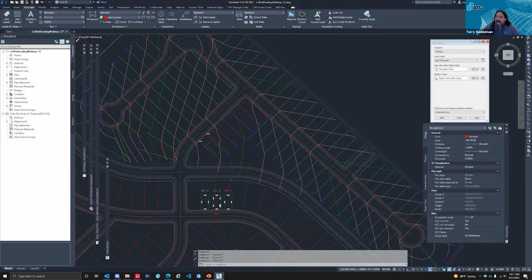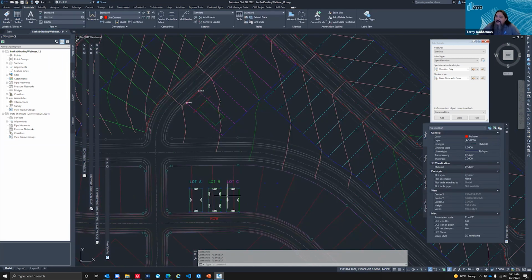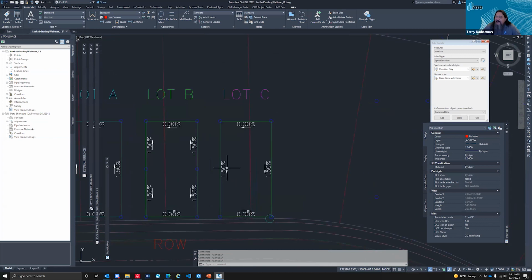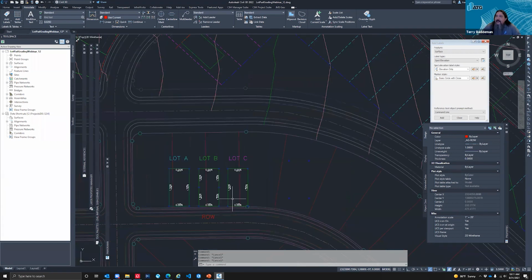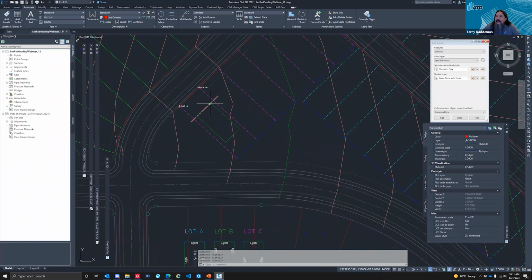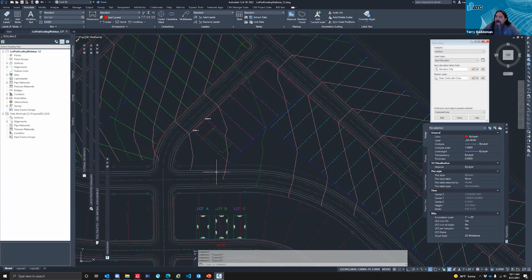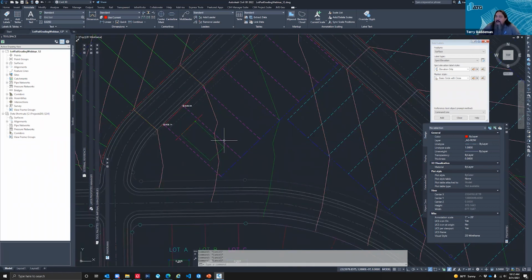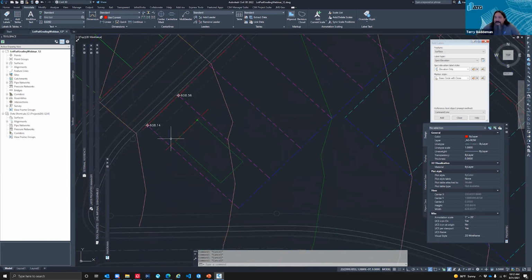The pad that I've used was this one here, which is basically sloping at 1.5% towards our roadway. So we're sloping down towards the roadway, and on our site here, we could actually identify this elevation and this elevation, and then continue on to copy our pads along our roadway. Very time consuming, very static, just a time consuming approach.